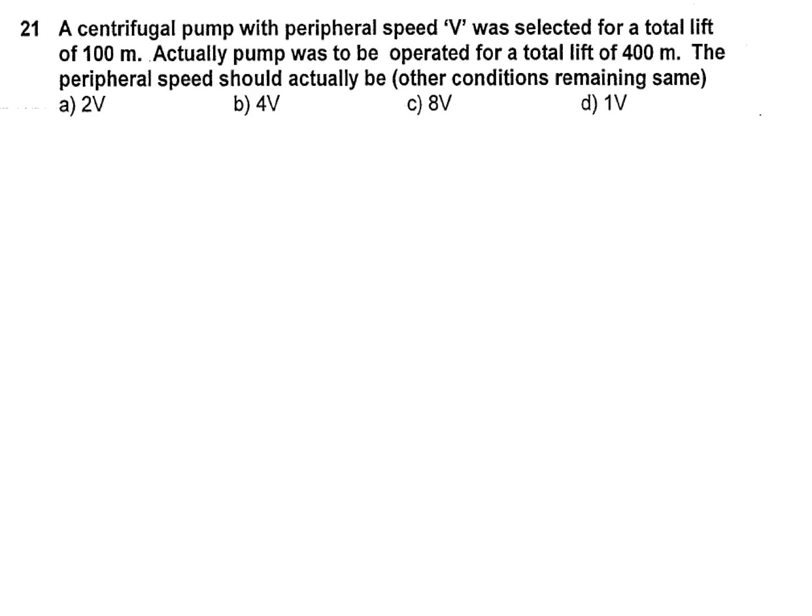So centrifugal pump, peripheral speed V. We know for a pump or centrifugal pump, power, head and discharge with speed: it's N, Q, n square, and n. In terms of diameter, it's d, Q, d square, and d to the power 5. We have to use this one.